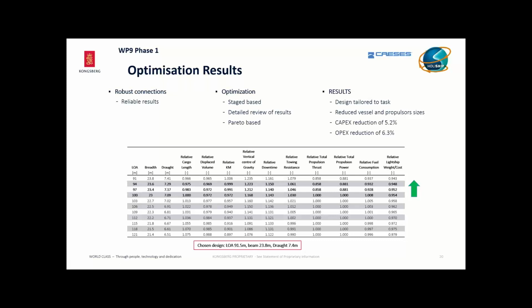And just by choice, we end up with a shorter vessel, much shorter than the starting one, but wider. That means that we have a different arrangement of accommodation and cargo space that gives a lower fuel consumption thrust required for DP operations. As this vessel doesn't have very high speed, they don't need to reach 16, 17 knots usually.